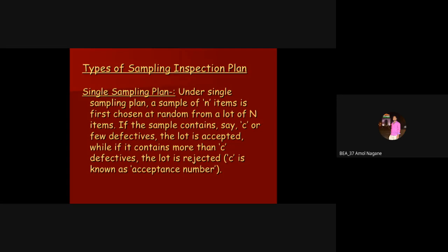But from the entire production we have to take only a sample. For example, within 1 hour, one nut and bolt manufacturing industry manufactures 1000 nuts and bolts. What is our capacity to maintain that quality or analysis? From the lot of 1000 we have to measure a minimum of 30. What percent is 30 of 1000? 3%. So we have to take a 3% sample. This 30 is nothing but C. The C value is the standard value. If the defectives are fewer than that, we accept the lot; otherwise we take the total lot of 1000 out.